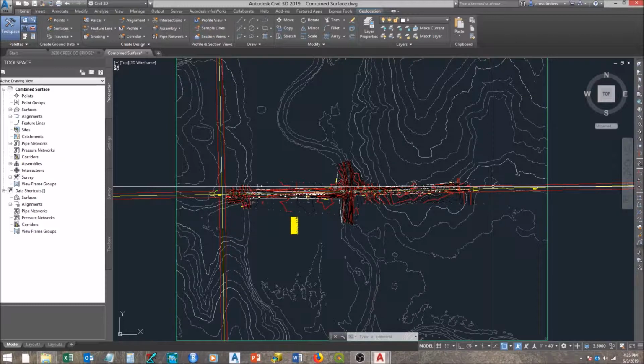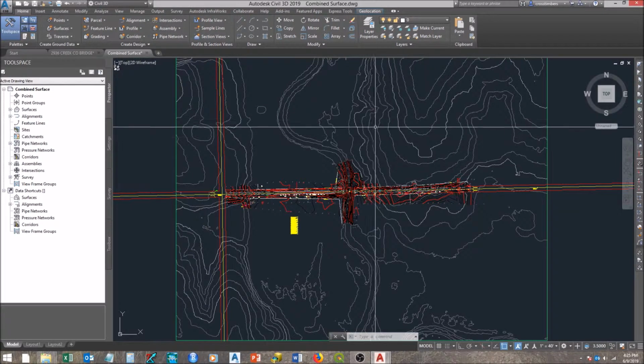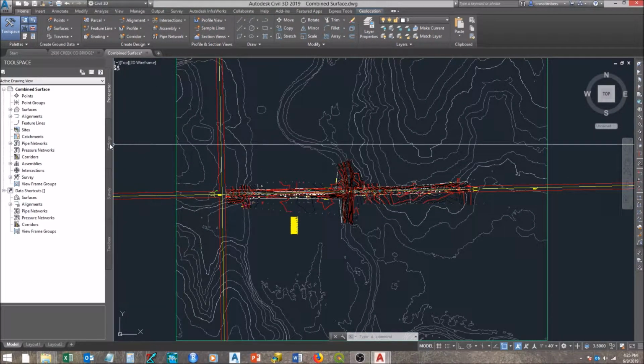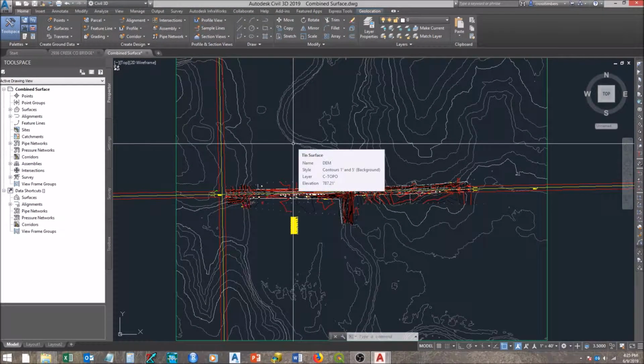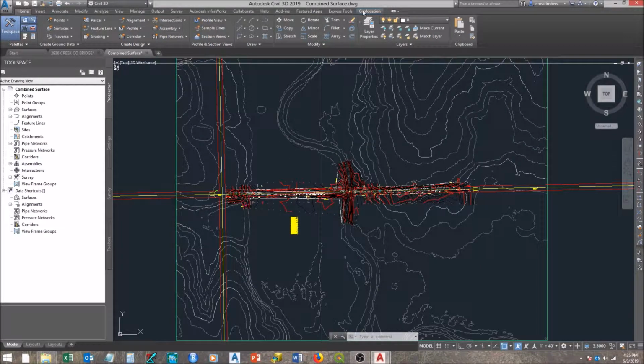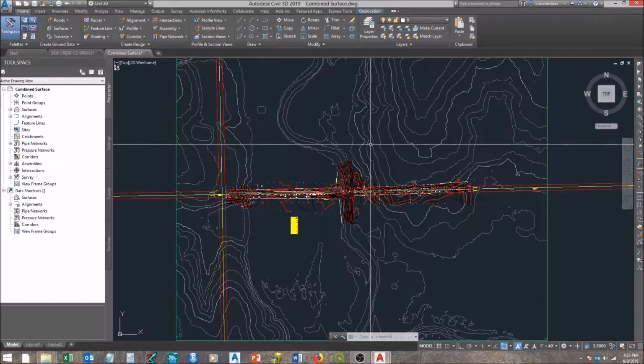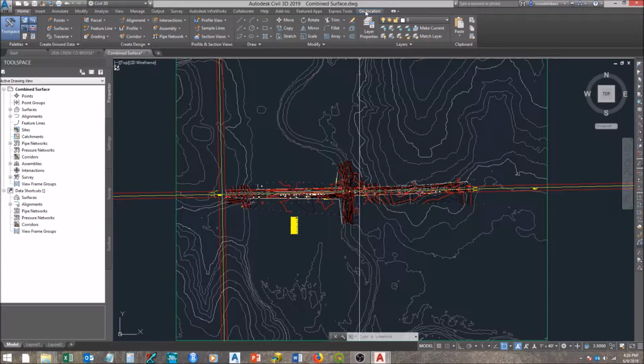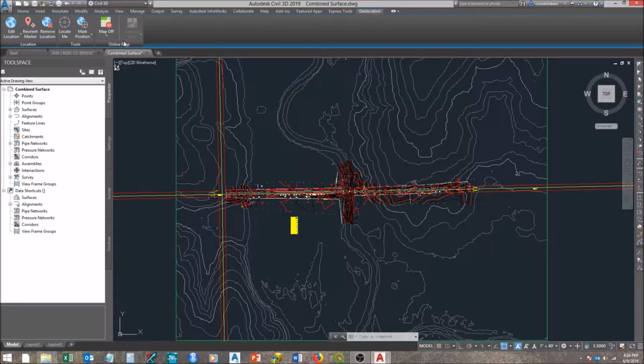And one thing I didn't point out in the DEM video is once you turn the settings on and define a coordinate system, you should have this tab pop up, which is a geolocation tab. And especially once you get your surface in, a good check to make sure it's in the right geographic location, you can go up here, click on this, and there's a mapping service.